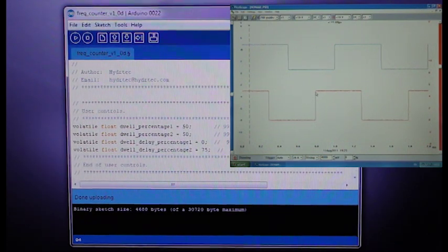Now, seeing as I've just set it to 75% of the input pulse period, I would expect it to be around here. We set the X position at 750 microseconds, or close to it. That's close enough. We see that the latency manifests itself once more here.